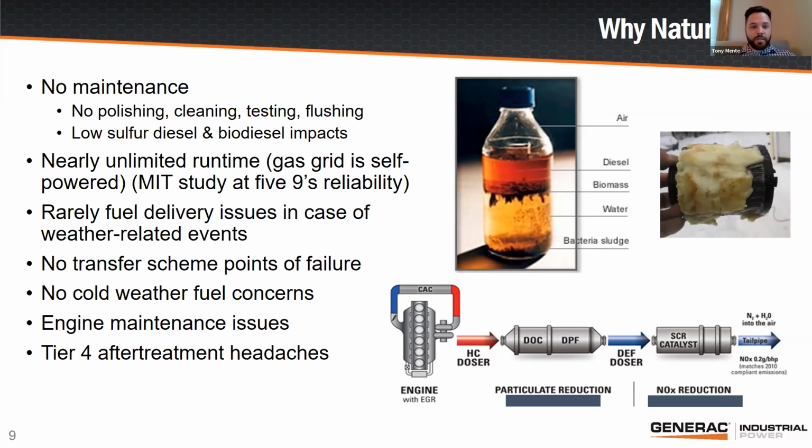Biomass starts to form, and so you have to do fuel maintenance annually, usually, on a diesel tank. And the introduction of low sulfur diesel and biodiesels actually makes that process worse, right? So you have to polish those fuels more frequently, and that is obviously added cost and complexity, as well as the fuel in very cold environments can gel up and freeze.